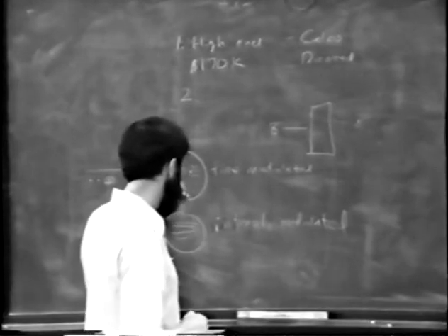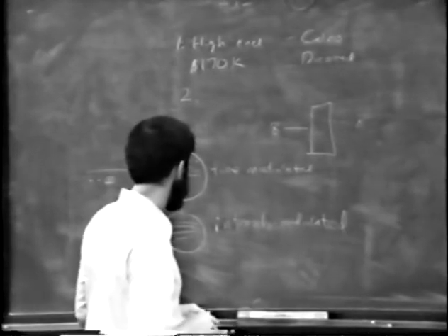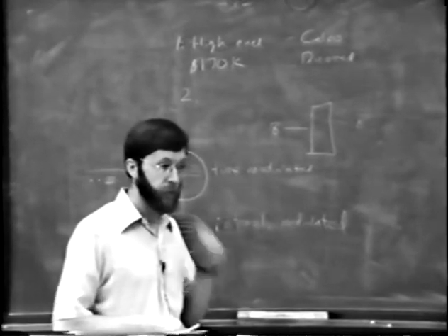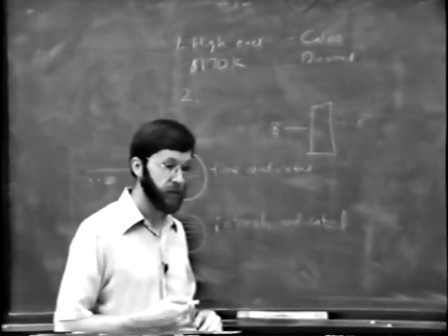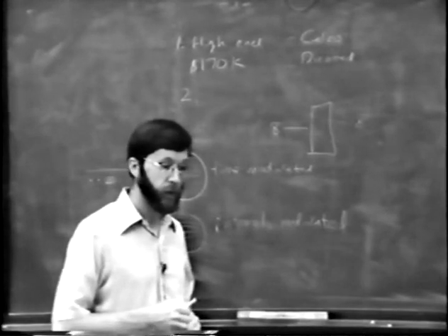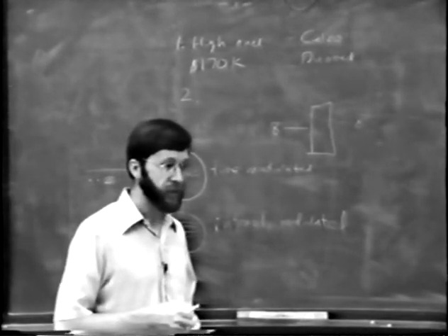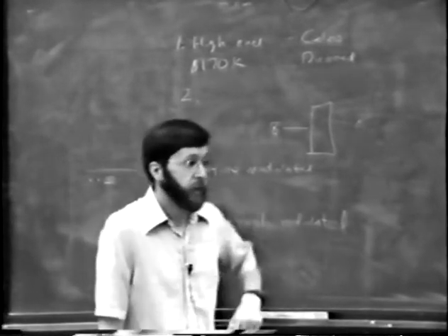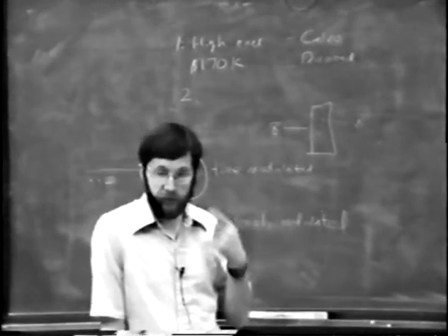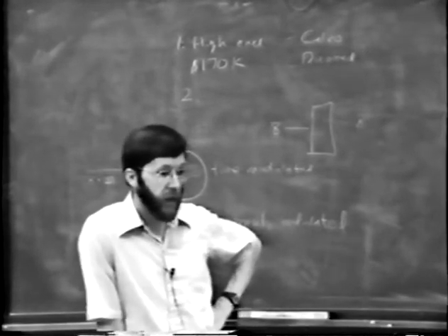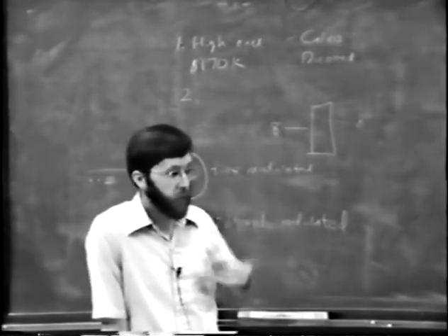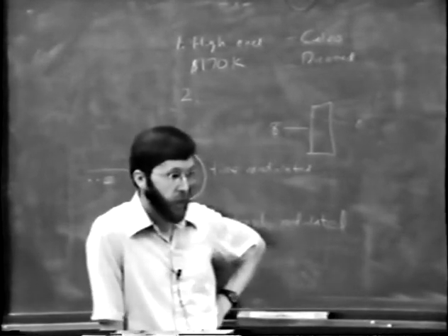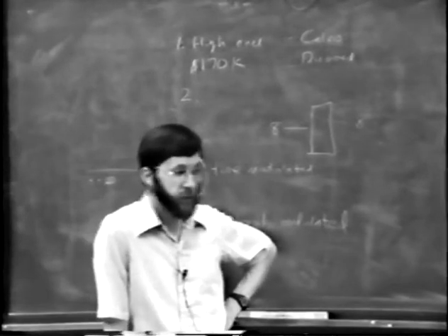With the intensity modulated, you of course have got the speed. It's just playing much, much faster. If you want the full dynamic range, then you typically don't want it going at video rates. That may be changing nowadays. There are now A to Ds and D to As, I should say, that are fast enough, and the circuit may be good enough that a good designer could have a thing which gave you the full range of what's possible in the system at video rates. Although typically with the Celco, we went slower than that.